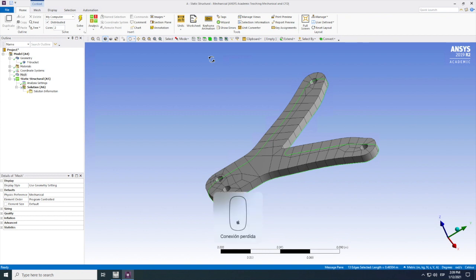A good meshing is the key for success, I would say. I'll just keep the control button on. Boom. That's the key for success. Exactly that. We just keep on selecting our edges one by one. Yeah, I like this more than in Fusion or in SolidWorks, where it's more automatic. You don't have so much control over it.